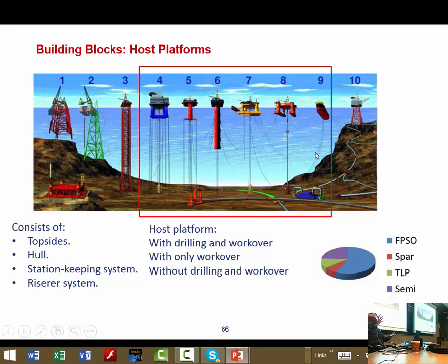First, for example, in our design, we calculate the maximum heave motion, and this maximum heave motion will be used to design riser system. Then riser system should be flexible for that. And for some solutions like this, TLP doesn't have any vertical motion. It just behaves like a fixed platform.